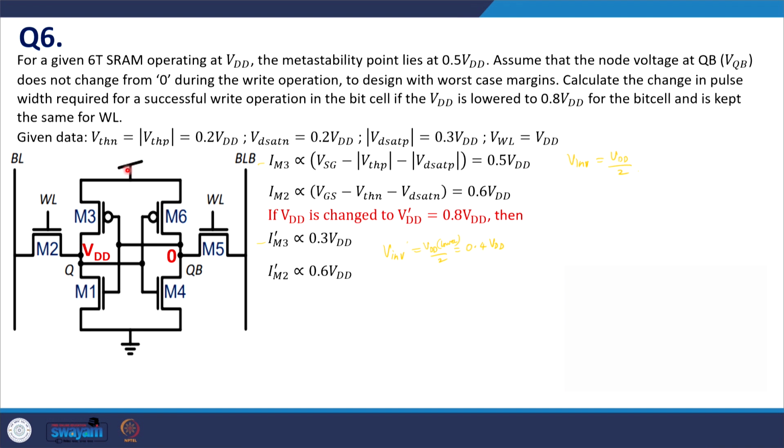As we have already discussed, the VDD of the cell is changed and VDD of WL is the older VDD, and VDD of BL is also earlier. So, to write 0, the bit line is at 0 and the bit line complement is at the older, earlier VDD.